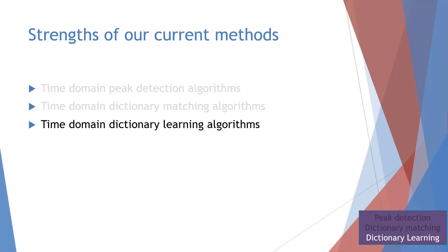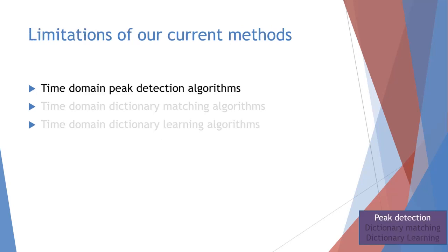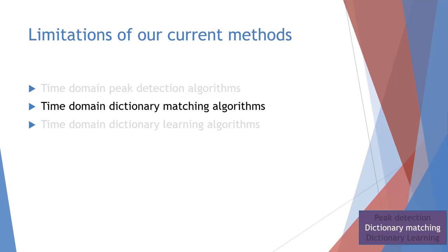Our peak detection algorithms are limited to cursory inspection of SSTDR reflections and give basic characteristics of reflections from faults. Furthermore, fault detection using this method is limited by the bandwidth of the SSTDR signal. Dictionary matching is limited to building the lookup dictionary by brute force and can be computationally expensive, depending on the size and complexity of the dictionary needed.